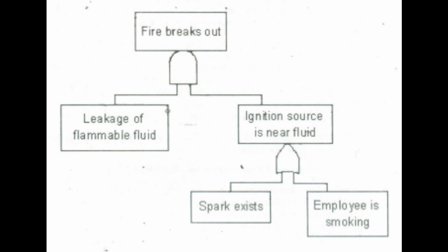Look at the screen. Fig. 5. A fault tree depicting the event, fire breaks out. Fault tree can be used in qualitative or quantitative risk analysis. The difference in them is that the qualitative fault tree is looser in structure and does not require use of the same rigorous logic as the formal fault tree. Fig. 5 shows a fault tree with top event, fire breaks out. This method is used in a wide range of industries and there is extensive support in the form of published literature and software packages, such as CARA. An application of fault tree analysis on causal relations for large vehicle accidents is documented in literature.